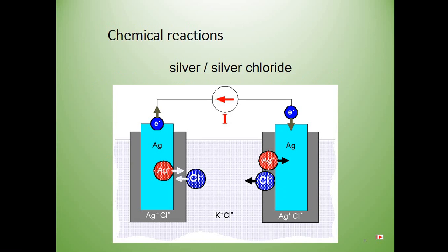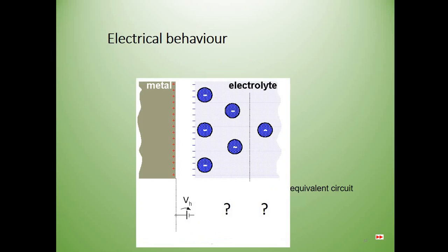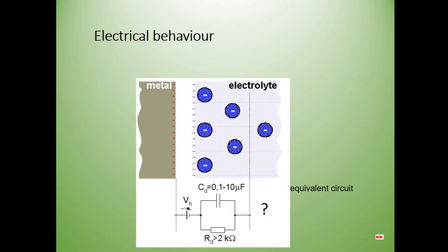So this is a pair of electrodes for measuring the biopotentials or a bioelectric event, and there is the Helmholtz double layer created, and the first charge difference is represented by the half cell potential, and later on the next level of potential gradient is represented by the parallel combination of a capacitance and resistance, and all the other components are represented by a resistor.